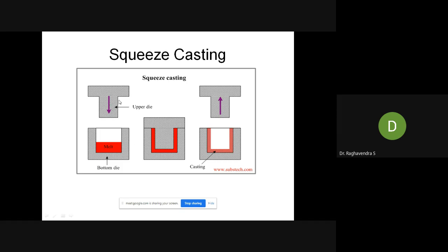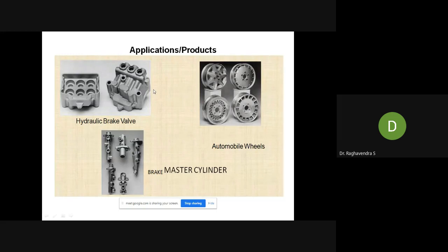Usually they manufacture piston caps and piston heads with squeeze casting. This is the simplest process, because they use simple geometry, not complicated geometry. There are no holes, ups and downs, curves, or fillets here.